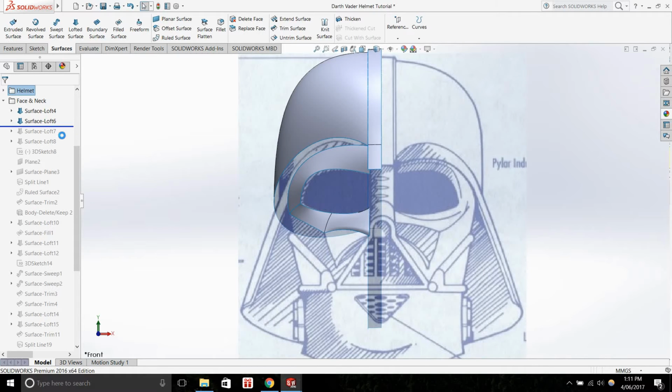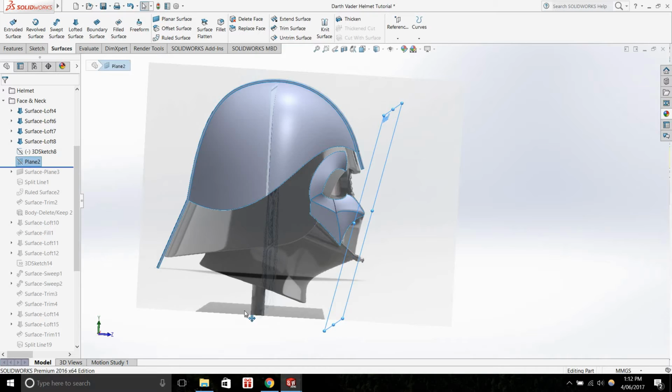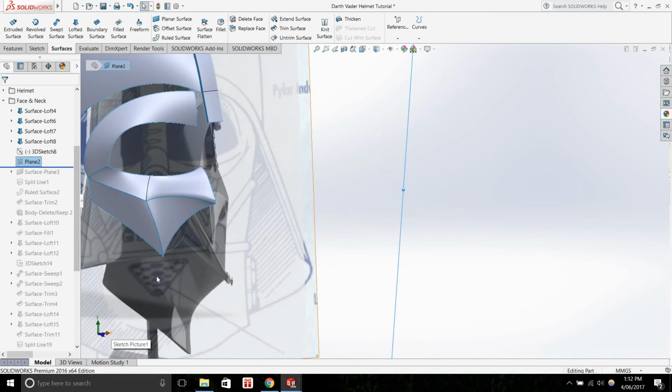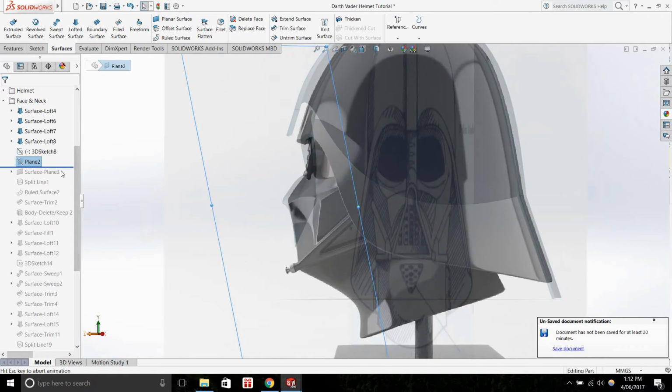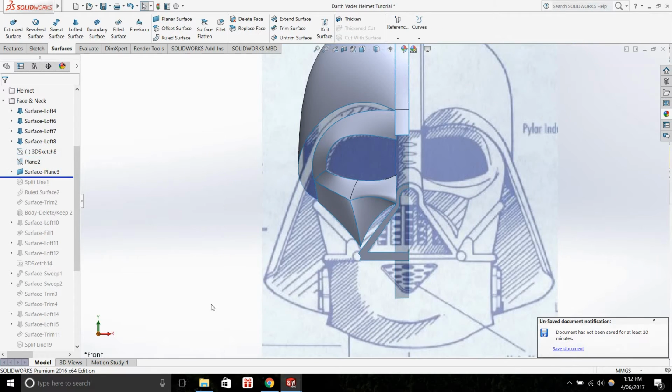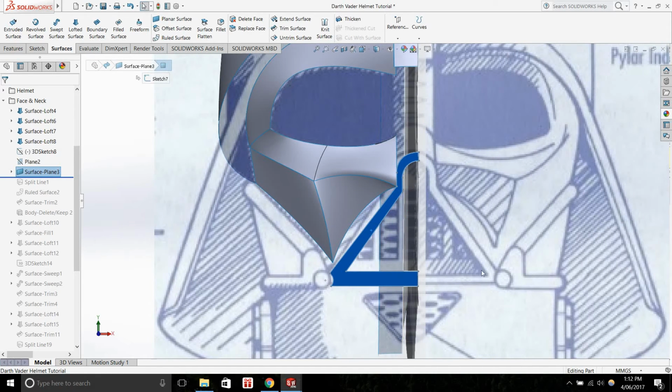And then just quickly going through this, I created another surface there, just around the nose area, another one there. You sometimes have to create planes to help with your modeling. So I created a plane there which mimics that front facial edge, and I did that to create that surface, which is part of that mouth feature.